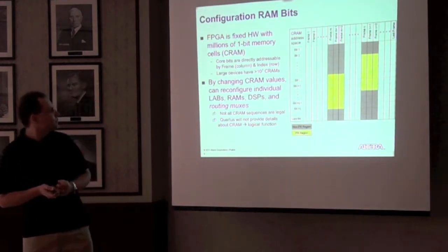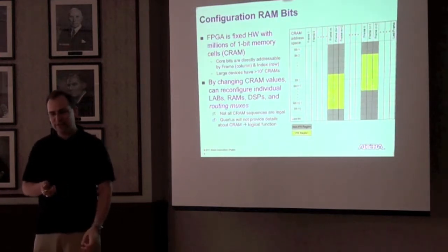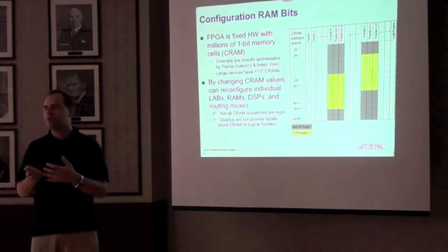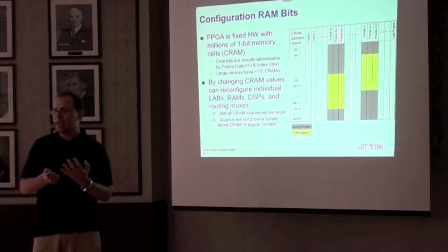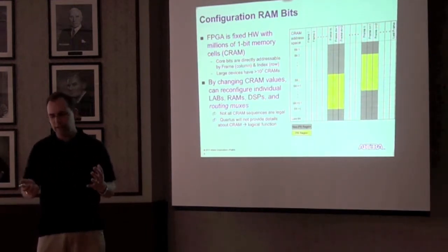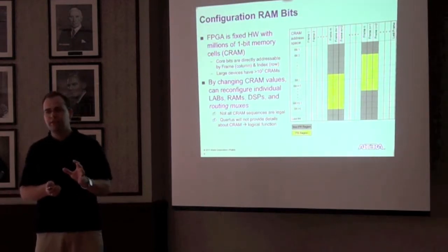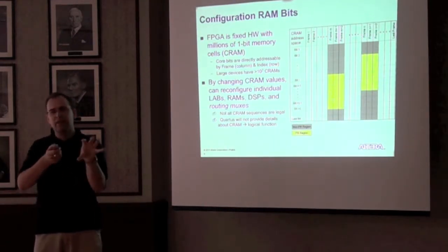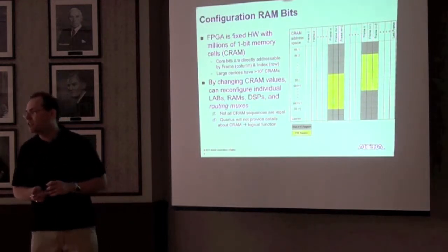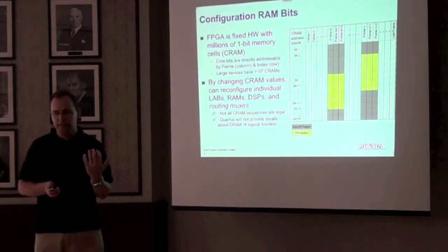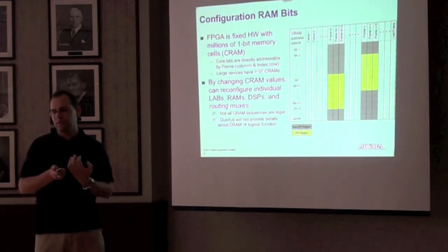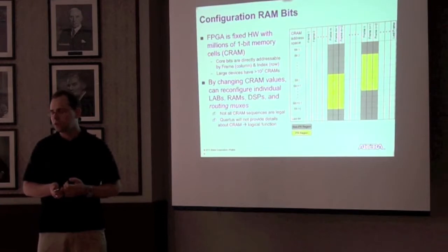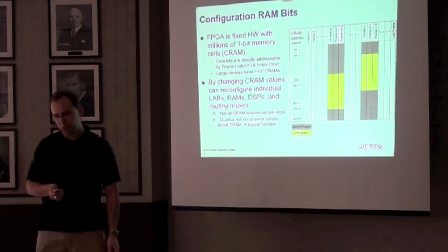Perhaps, much to some people's dismay, neither Quartus nor Altera will provide any details of how individual CRAMs map to logical functions. So being able to directly get in there and look at a grid of what these CRAM bits are and say, oh, I want to change this to 1, this to 0, and I know exactly how that will implement the function, that will not be supported. Instead the software, Quartus, will be the only vehicle to implement this coarse-grained reconfiguration that we support.